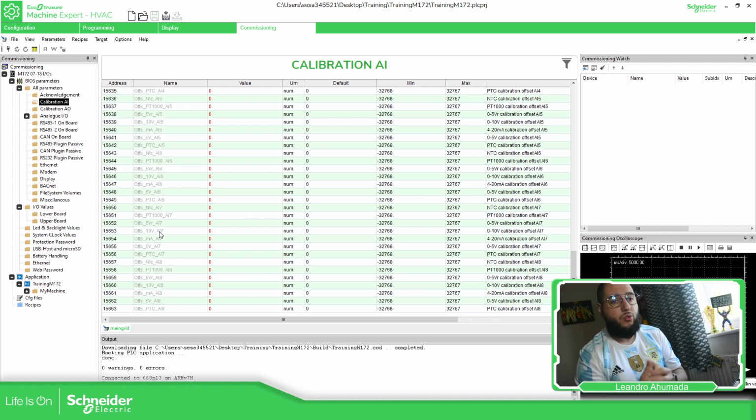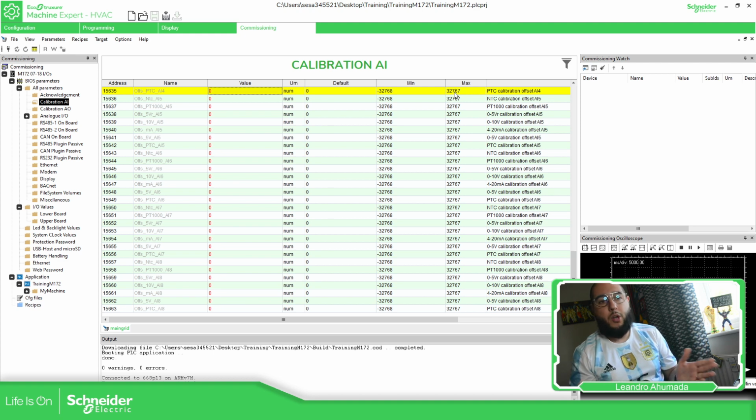Probably I'm used to play with other PLCs and I do this outside. For example, I make that small calibration in what's called the configuration of the hardware. So for example, the raw value, we know that it can be from this to this, but probably I can scale the function to go from 0 to 1000, or that it gives me the value. So that is another option.